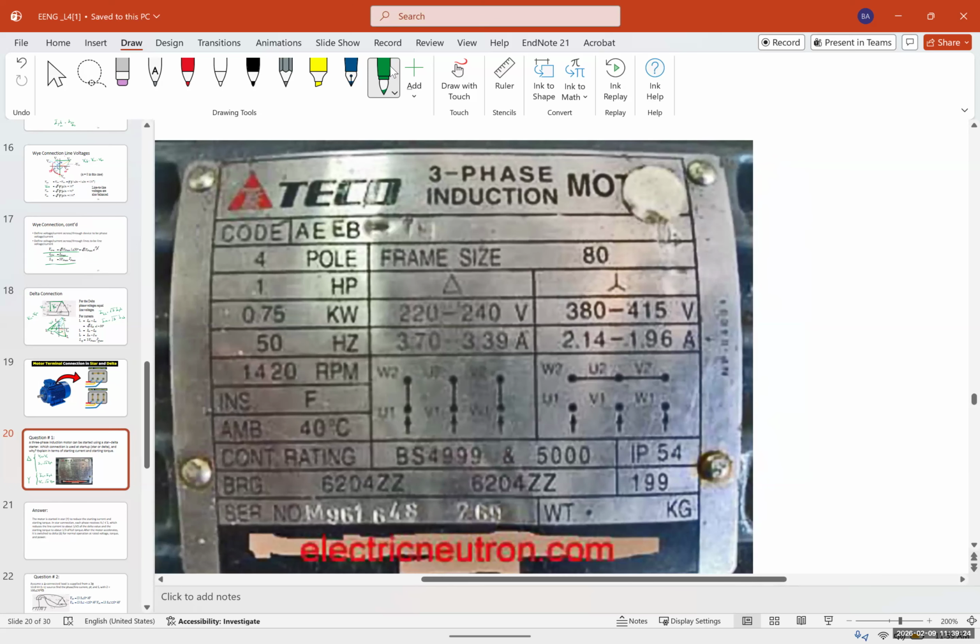Now, depending on the order that we connect them to phase, it's going to be a clockwise or left turn, what they call left turn, right turn motor. So by just switching these 2 phases, for example, you can determine the direction. So if you have an elevator, you want to go up and down, you would just change these.